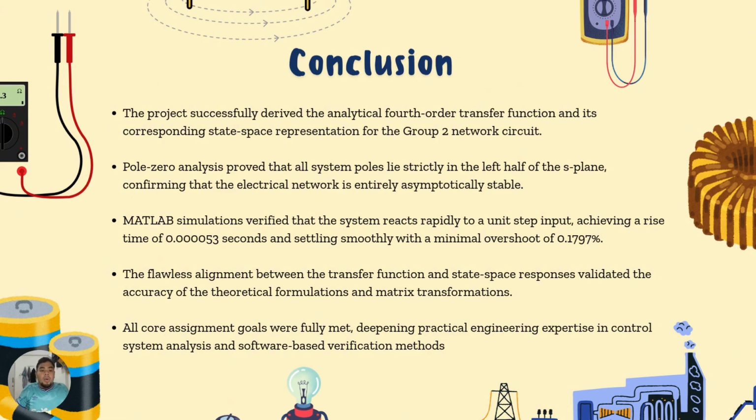After that, we did the MATLAB simulation to verify that the system reacts rapidly to a unit step input, achieving a rise time of 0.00053 seconds and settling smoothly with a minimal overshoot of 0.1797%. The flawless alignment between the transfer function and state space response validates the accuracy of the theoretical formulation and matrix transformation.